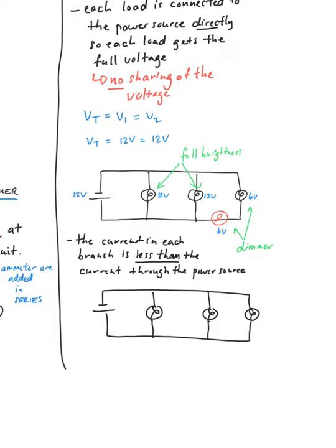Now when we go over here and we're looking at a parallel circuit, when the energy goes out to this unique branch, we're going to get a different reading. As the electrons are flowing, keep in mind that current is a measure of the charge moving past a point in a second. When the current is flowing here, it has to divide and go down the 2 branches. So some of the electrons will take this pathway and the rest will continue this way. Then I'll lose some more as they split down that pathway, and so on, so the current flows down different pathways. It will get divided.